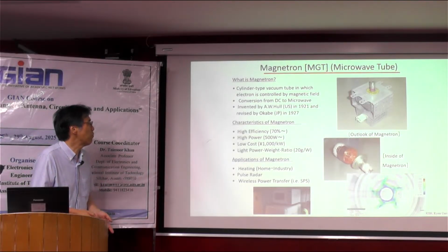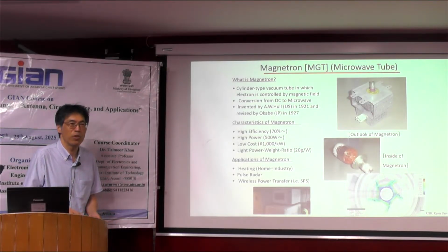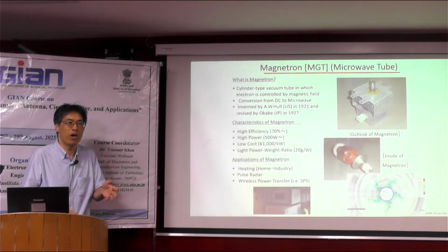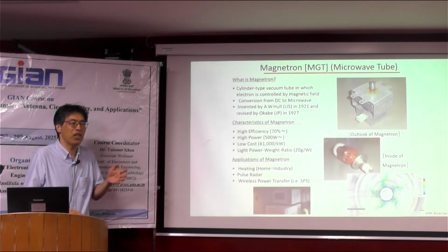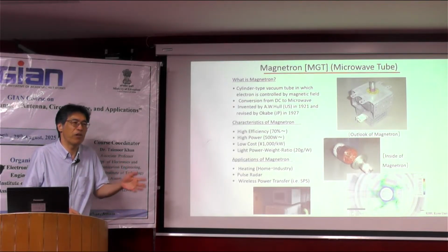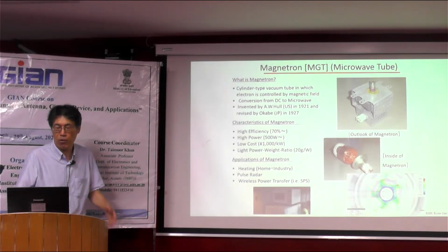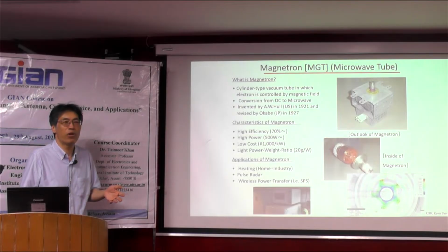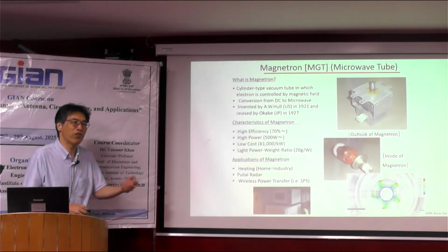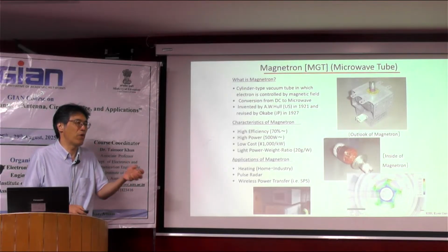We have some kinds of microwave tube. The magnetron is usually applied in your house, in the microwave oven. The other types of microwave tube are the klystron, TWT (traveling wave tube), or gyrotron, etc. For wireless communication, now they do not apply the magnetron. About 50 years ago, they applied the klystron as a source of wireless communication.